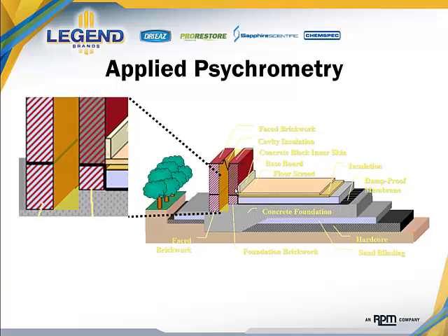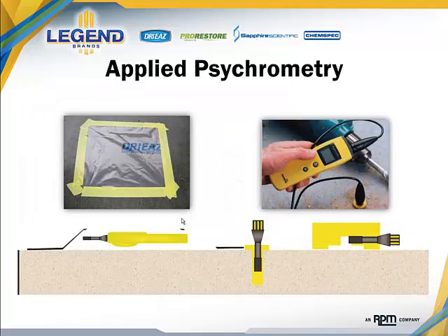If the humidity in that cavity, in other words, is 90% or 80% relative humidity, then it doesn't matter what your dehumidification systems have created inside the living space. That air is not impacting that assembly, and it's going to dry slow. It's going to take weeks upon weeks to dry those building materials. However, if I can get the humidity in that cavity down to 20, 30% relative, then the drying process will be dramatically faster. There are lots of ways to use hygrometers to measure different types of surfaces, to evaluate whether or not the humidity is appropriate in those areas.